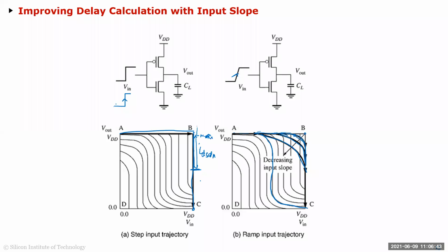So this is a little bit of a complicated calculation. People actually characterize this straight from SPICE, and they feed this as a function of your rise time straight into the .lib file. And when we go into the .lib file, we'll see how they're fed into that.